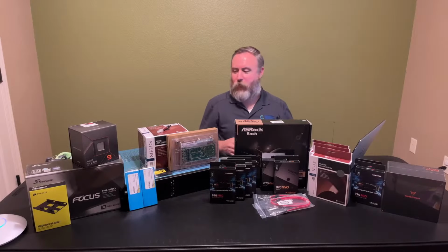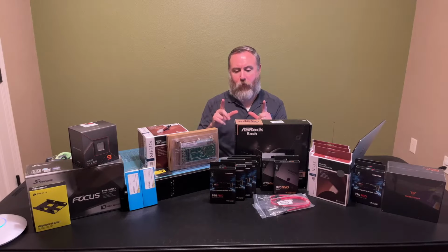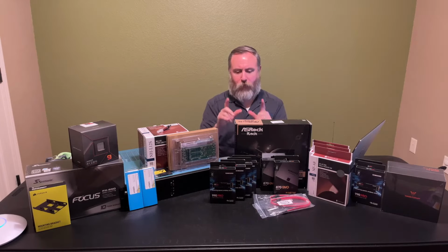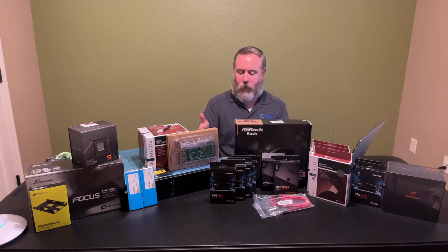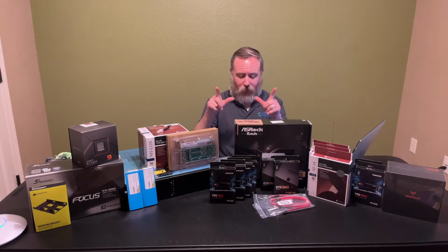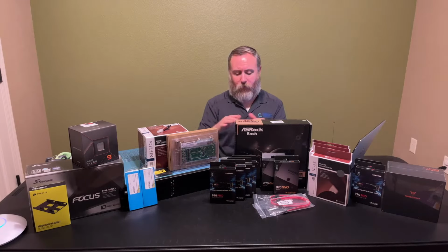So basically what I did, and I don't have them right here with me, is I bought these 140 millimeter magnetic fan grills. So they have a little magnetic strip around the perimeter of that square fan grill. And what I did is I took some nibblers, which allow you to cut very straight lines in the center of metal, and I cut out a square hole right above where the heatsink of this Noctua cooler is, and then I stuck one of those magnetic fan grills, or magnetic mesh filters, on top of that.